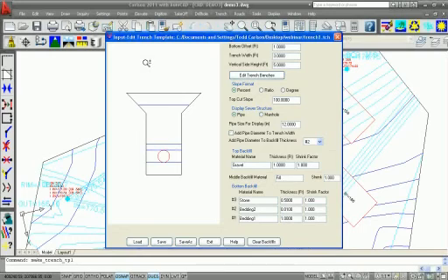So when they ask the engineer for the PDF file, is this something they should be specific on? Does it automatically come in design when we're doing sewer layout for road work, or is it something omitted? Yeah, it's something they should ask for. If they're doing any estimating or utility work, what the trench is going to be for those utilities is something that should be provided to them. So once they get that, we can not only create the trench, but size it to the exact design that we want, with all of the materials added, which you're filling in at the bottom there with maybe crushed gravel and so on and so forth.